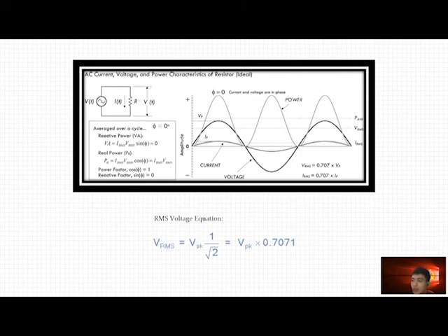These effective values don't average out to zero; they are essentially the AC equivalent of DC voltage and current. RMS values of AC voltage and current are based upon equating the values of AC and DC power required to heat a resistive element to exactly the same degree. The peak AC power is required for this condition.